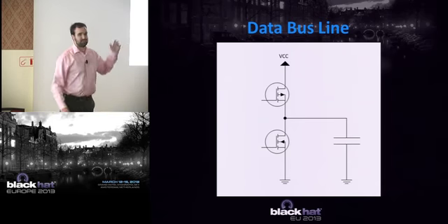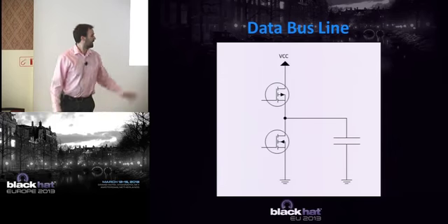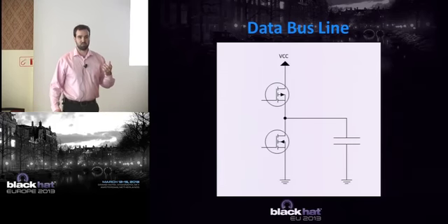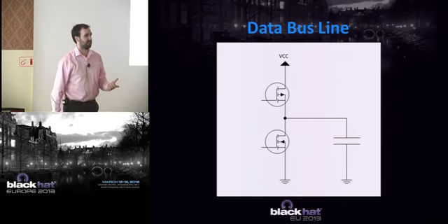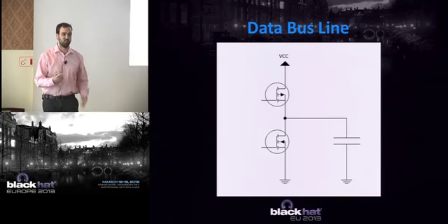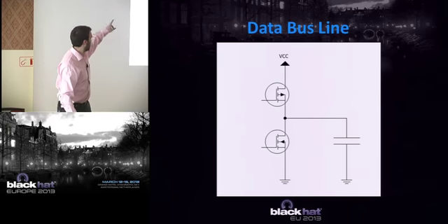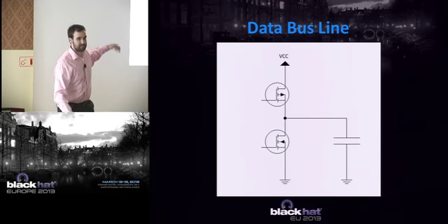Now, this bus, which is effectively a long wire, relatively, has a bit of capacitance. To change the state of a capacitor, it takes charge, which means it takes power. So every time we send a 1 or a 0, it takes a tiny, tiny, tiny amount of power from one of those, either the VCC or the ground rail.